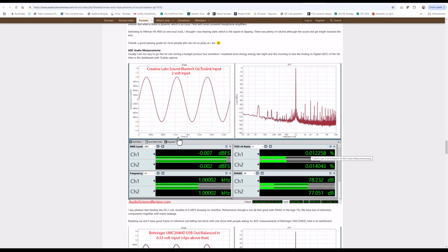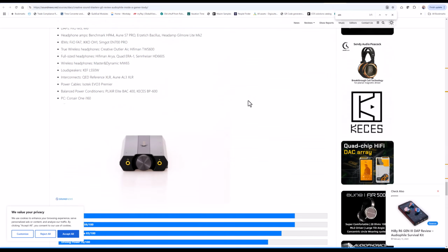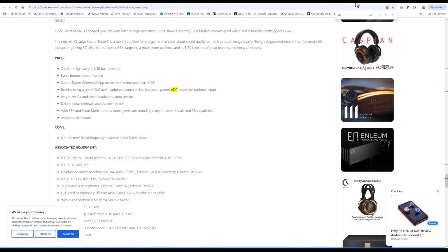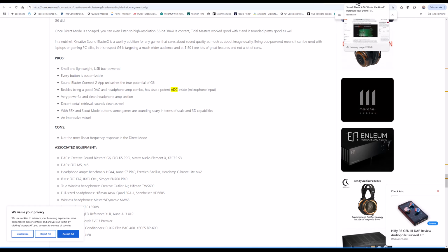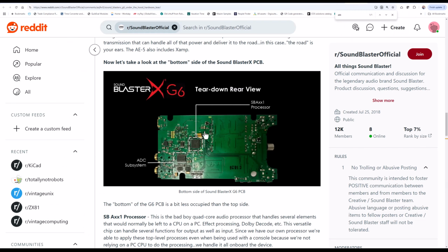And I found some teardowns of this thing, some pictures inside here, and I asked ChatGPT what A to D converter is used in this thing. Again, people seem to focus on the DAC for some reason, and here's a picture of the ADC. I think I have cracked it open before, and I'm pretty sure it is this device here, the Cirrus Logic CS5361.